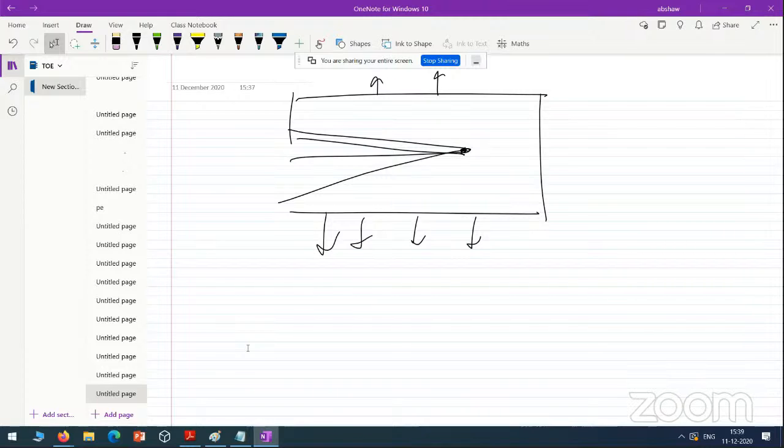All the components are non-zero, but all the stress components associated with the z axis are zero. So you have sigma xx, sigma yy, and sigma xy non-zero, and sigma xz, sigma yz, and sigma zz all zero. But it doesn't mean that your strains are also zero. It doesn't mean that your epsilon z is also zero.